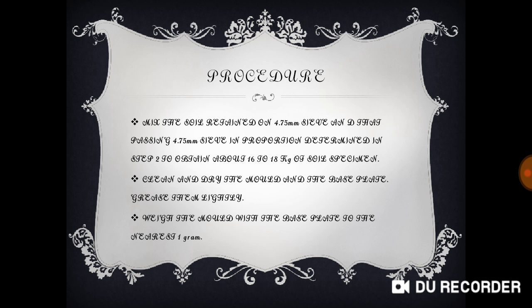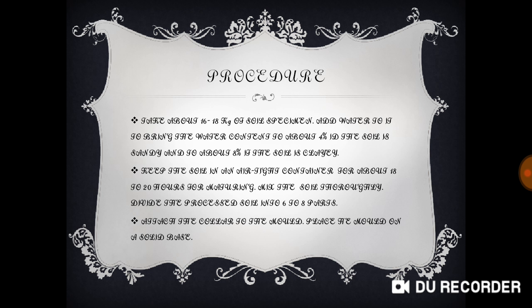Weigh the mold with the base plate to the nearest 1 gram. Take about 16 to 18 kilograms of soil specimen and add water to bring the water content to about 4% if the soil is sandy and to about 8% if the soil is clayey. Keep the soil in an airtight container for about 18 to 20 hours for maturing.